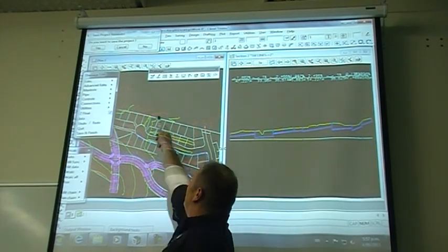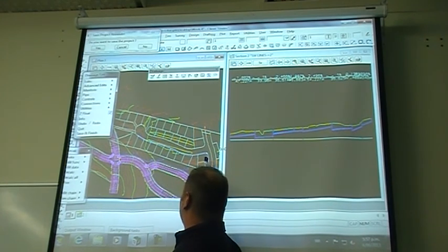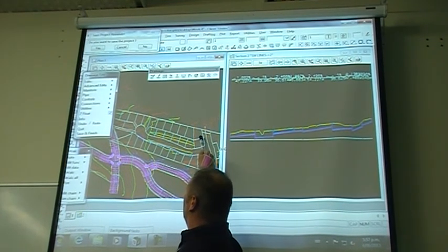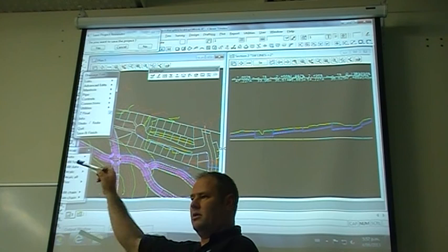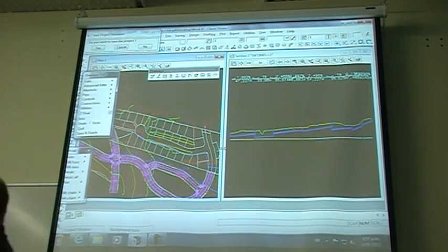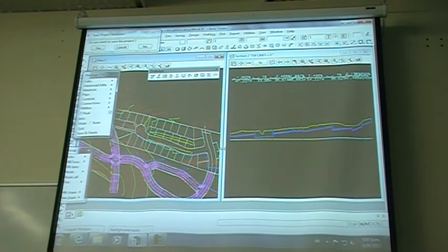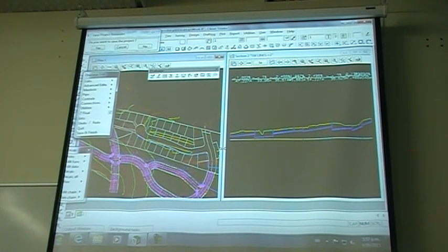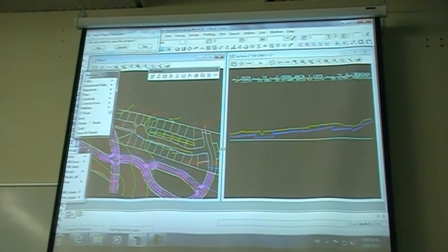When it's dead flat, and you'll see when I get on to making a couple of extra stormwater lines, the preference is to try and come up in the middle and pick the sections off either side, so you can do both of these. You understand, if it's pretty flat and we're not looking at a major difference from one side to the other, then the ideal is to serve all of those lots from one central line, so that you've got half the pipe, half the manholes. Okay, it's just going to come down to your judgment call.